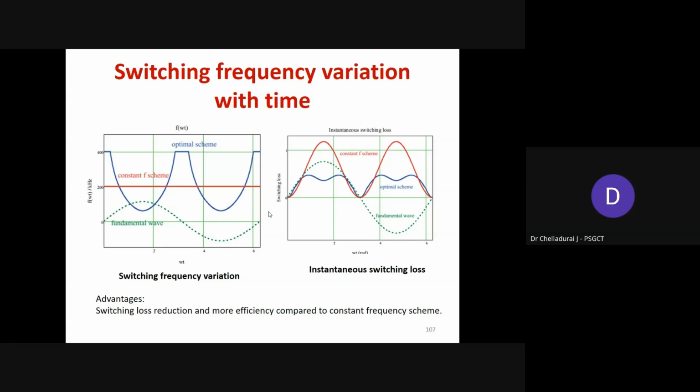If the same motor is running at 100% load or rated load, then under rated load condition, instead of using a higher switching frequency, we have to use a lower switching frequency. So based on the load demand, we can change between the lower switching frequency or higher switching frequency mode. Another very interesting piece of information.